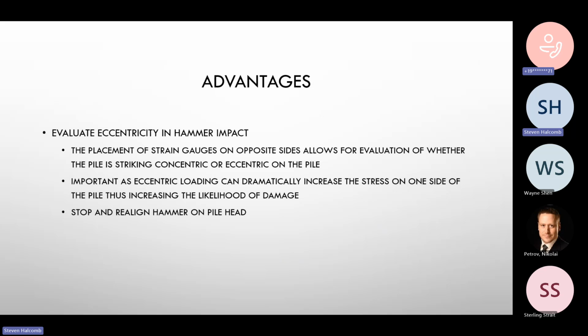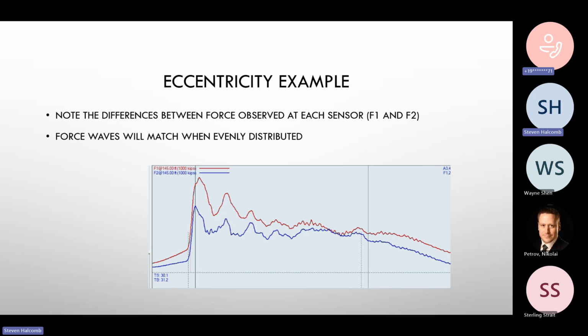And like I said, it increases the likelihood of damage, and you realign it if that's what you see is going on. But that takes a bit of experience working with your crew. Maybe the first pile you don't necessarily know it, but usually by the second or third pile you can tell that your crane operator is maybe not paying attention. And I know he wasn't, because he was on his phone most of the time. I won't call out the company, but they were nice guys.